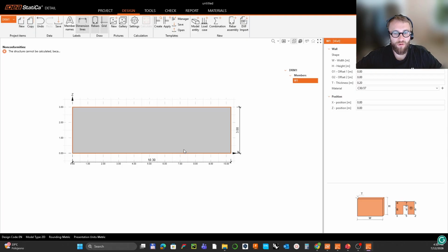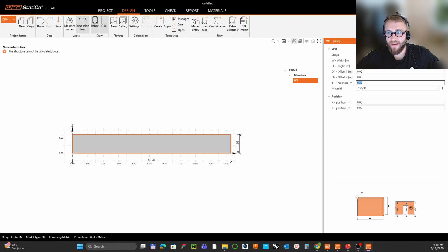But actually, for this part, you will be specifying the base plate or some width of the support, and I would like to have it directly above the supports, 10 meters, and the width of the plate on the bottom edge is basically 30 millimeters from both sides. So if you are in the middle, you need to specifically define this 10.3 millimeters distance to have it precisely 10 meters above the center of the support. So 10.3 millimeters, the height is 1.2, and the thickness is 0.025.